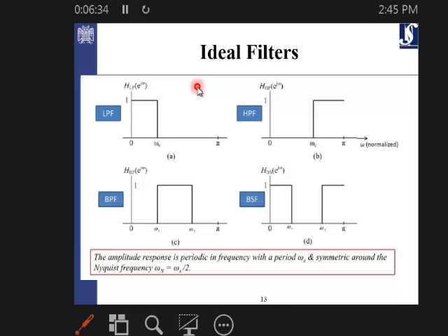So you have to get rid of these noises. If you know exactly where the noise is, so if the frequency of the noise is clear, you can put a filter in such a way that that part of the frequency is ignored, and you just get the part of the signal which only belongs to the signal. In some cases, or in many cases, you don't know exactly where the noise occurs.